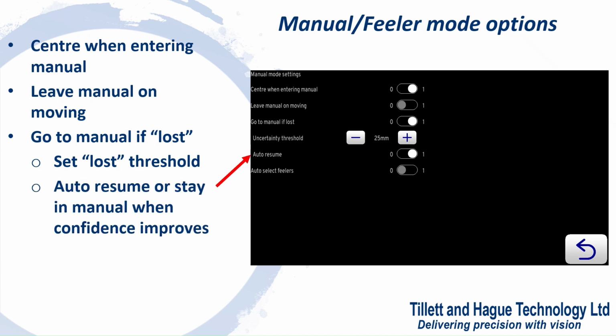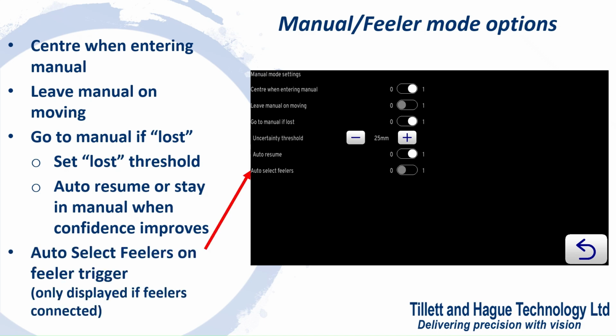If auto resume has been toggled to on, tracking confidence is monitored while the guidance system is in the lost mode. Once the level of guidance uncertainty has risen to a suitable level for enough time, camera guidance can automatically be resumed. If feeler override ones are connected and activated, when they make contact with the crop row, this preference allows automatic engagement of feeler override input to control guidance.